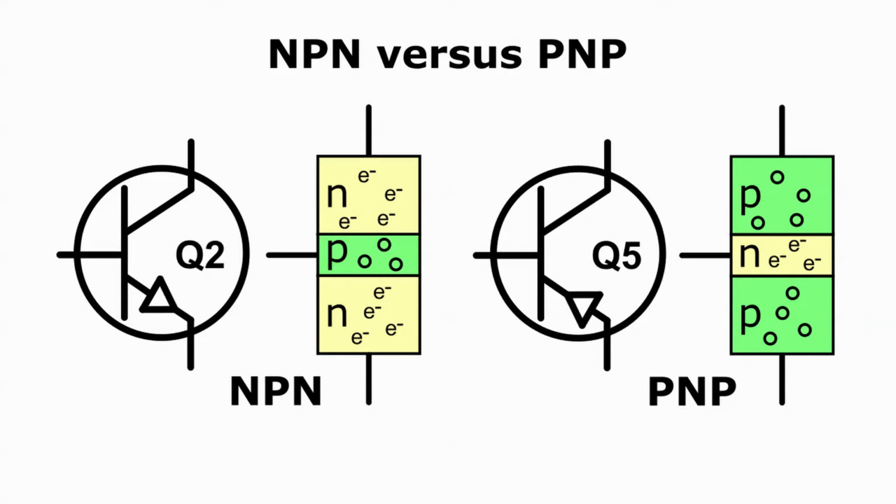In fact, the difference between a metal and a semiconducting material is more a matter of degree than a black and white characteristic. Even the tiniest voltage will move electrons in a metal. In a semiconductor, on the other hand, there's a threshold voltage, in the order of a half volt or so, that has to be exceeded before the electrons move. A P-type of material is one whose atoms are ready and willing to accept an electron into their outer layer